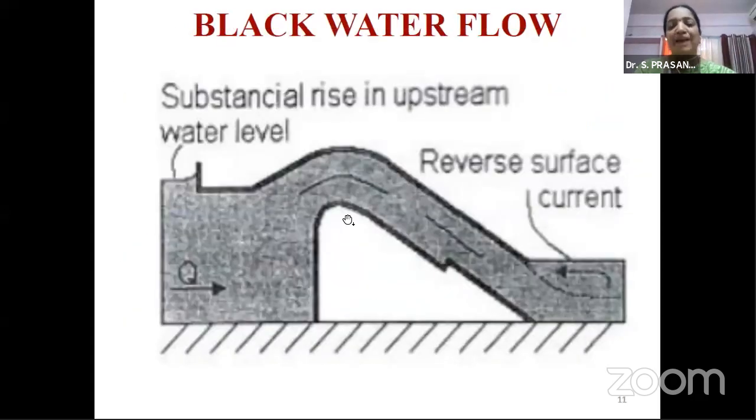This is what is black water flow, where the level of the water has risen over the lip level and there are no traces of air seen in the hood portion, and at the same time the complete hood portion, the outlet on the downstream side and the inlet are completely sealed only and only with water. So these are the 5 different stages of the siphon spillway.